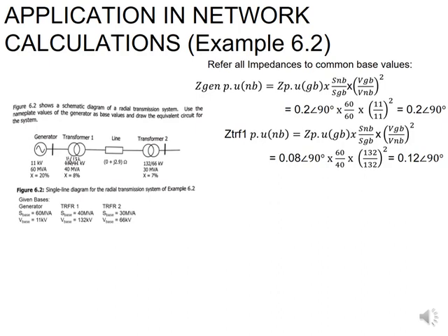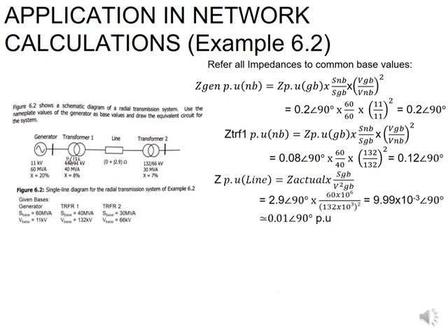So you put the voltages or you don't put them in, they don't matter because they're always going to be the same value. And you can utilize either your HV voltage or your LV voltage. As we had said in the 6.1, your impedance is going to be the same, whether you're on the LV or on the HV side of your voltage.